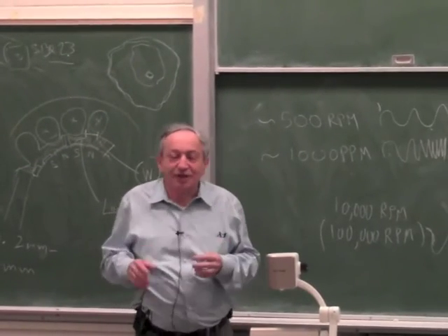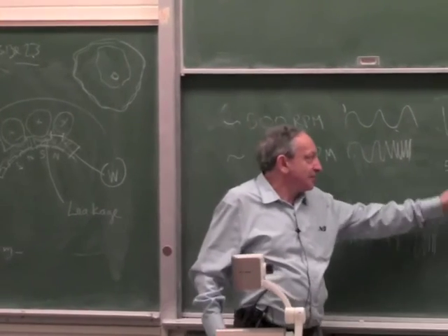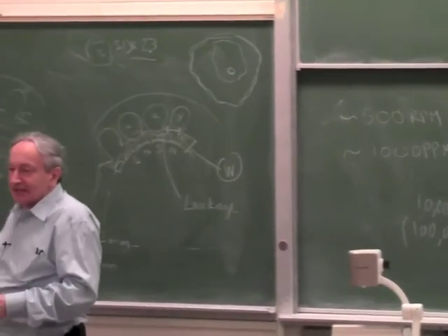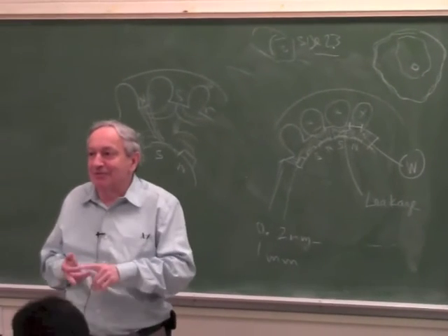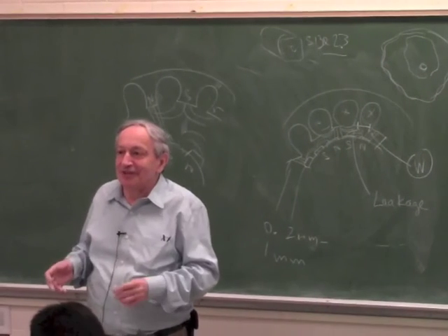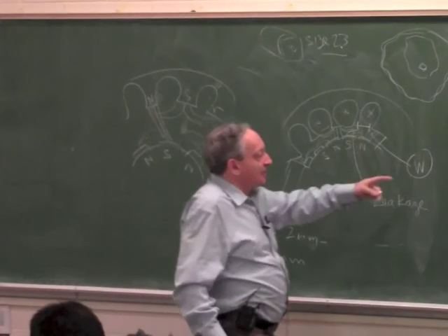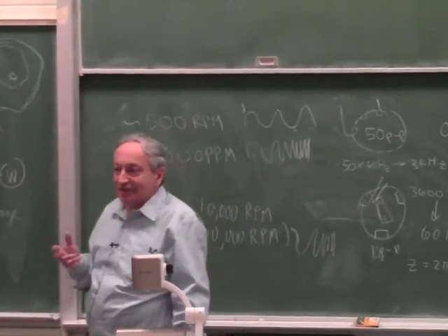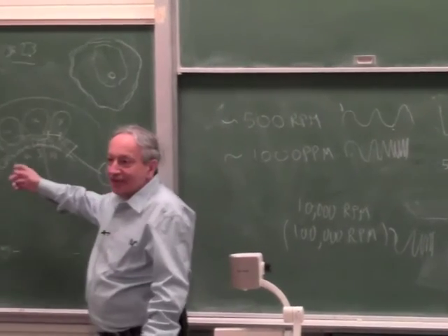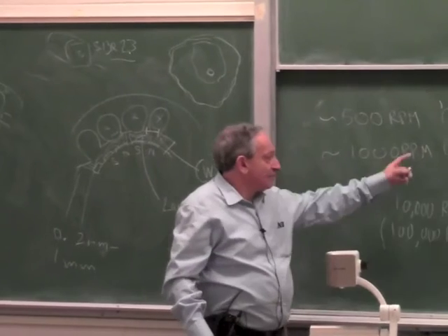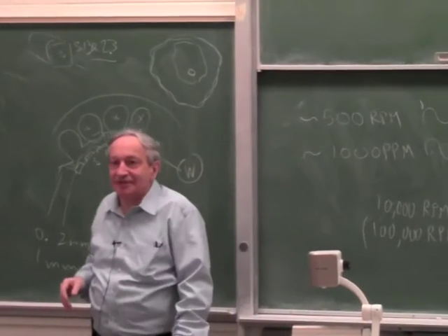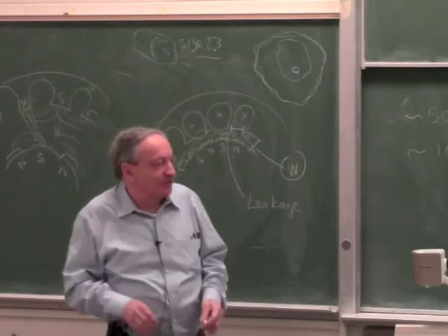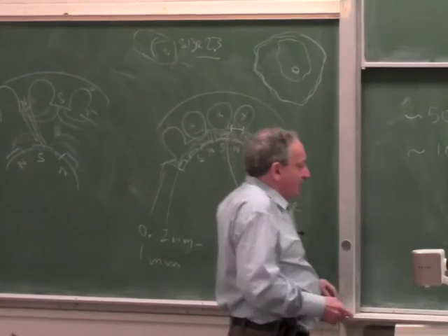So functionally, a synchronous motor and a stepper are exactly the same motor. But practically, when you start analyzing efficiency, torque, maximum speed, they behave a bit differently, because increasing the number of poles to so many poles has some penalty on leakage flux, on efficiency, on maximum frequency, on a whole bunch of things. Is that clear? Good.